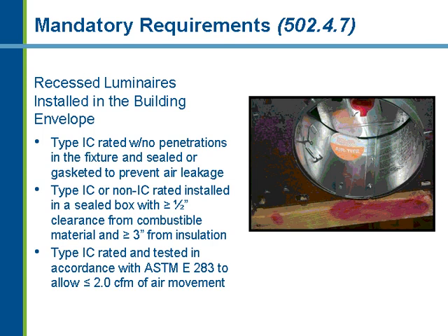But if it's installed in the building envelope, you have a few different options for meeting the requirement. One is you want to put in a can light that can have contact with insulation. That's the Type IC insulation contact can light. So you want to make sure that you have pretty continuous insulation in your roof ceiling assembly. And then you want to put in a can light that's sealed up or fairly sealed up by code so you can reduce the infiltration losses out through that can light. So you have three different options available to you to meet the code requirement.